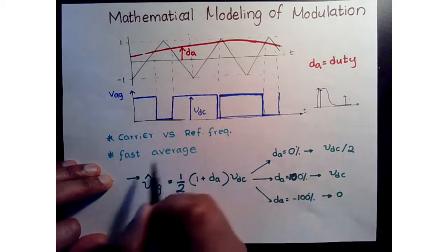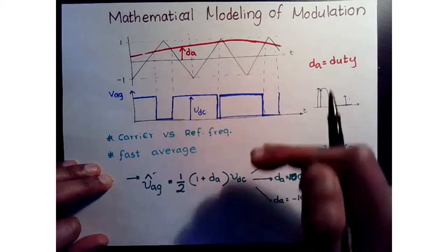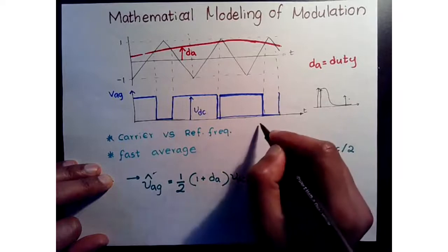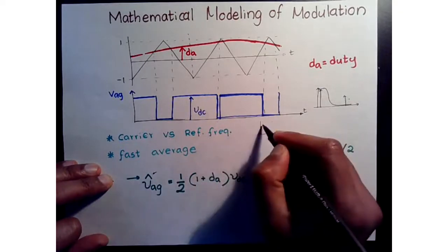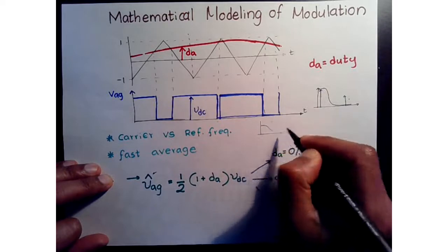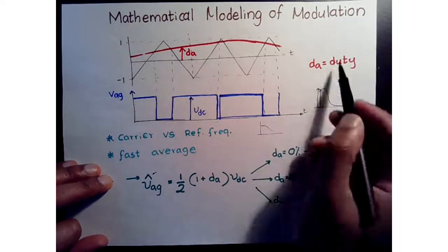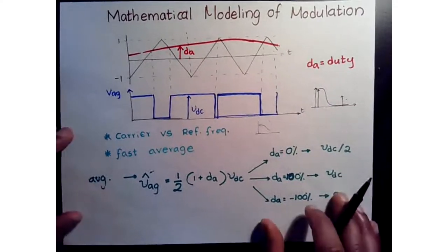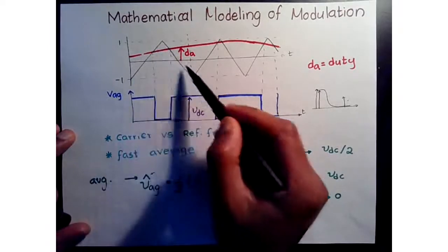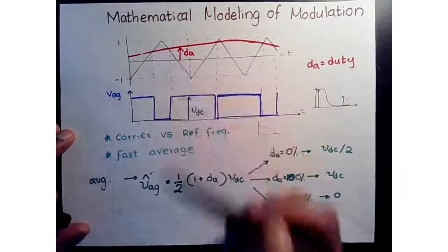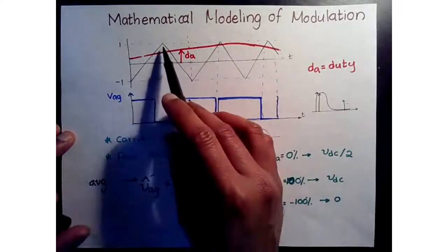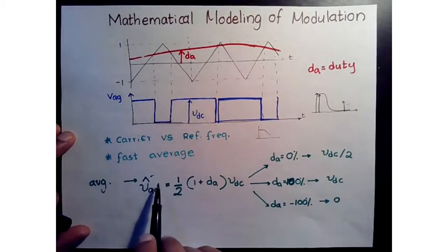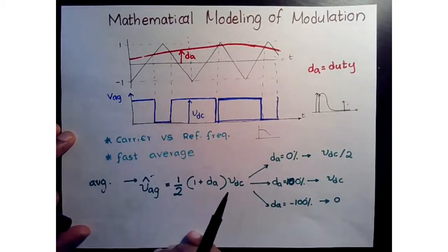So basically, from this point onwards, even though it's a PWM inverter, the voltage that we see is called a fast averaged signal, where it looks like it's following a sinusoidal nature based on what we apply, right? Following the duty that we apply. Okay. All right. So here we are considering a duty that varies from -1 to +1. And then depending on the duty, we are going to see 3 primary states, and of course everything else is going to be in between.